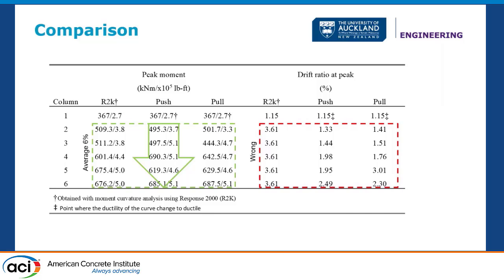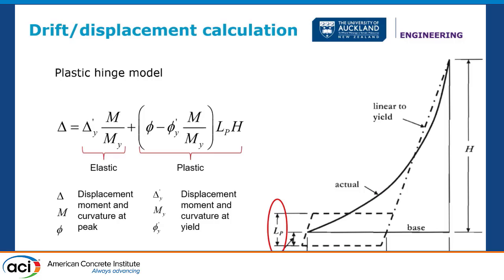Why is that? Because all the theories, and now I'm going heavy into seismic, so I apologize if you're not familiar with seismic design, all of the theories are based on steel reinforced concrete. So they do not include not only the FRP properties, but the synergies of how the FRP behaves with the concrete, which is the critical part here, because FRP debonds, and that is an inelastic mechanism.